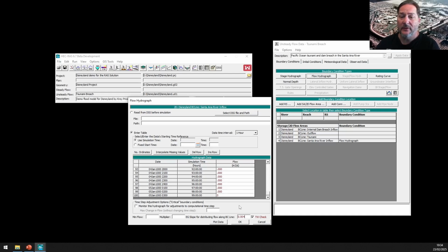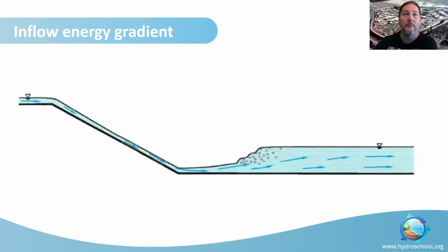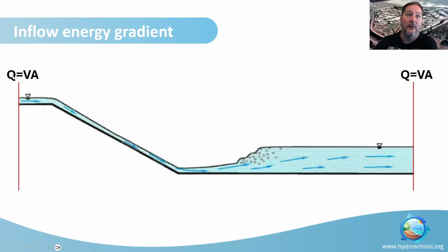So why does this matter? Well, if we take an example here of a varying longitudinal slope and say we wanted to assign a boundary condition here as an external inflow, you would have a given Q, a discharge in cubic meters per second in our case, coming in at any given time step. Well, HEC RAS knows nothing about the terrain upstream of that external inflow boundary condition. So should it bring in the flow at this depth or at this depth?